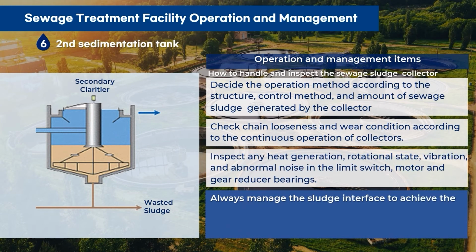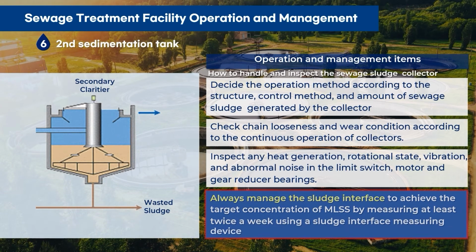The sludge interface should be checked at least twice per week and continually managed in order to achieve target MLSS concentration.